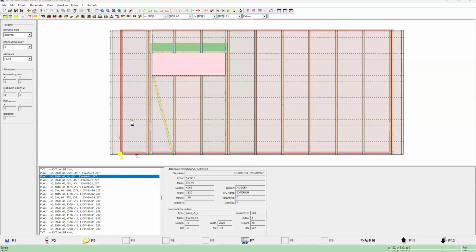ArchiFrame has added markings for every fourth or third cladding piece, because the operator places these manually on the table, and then the machine shoots the nails, and it has to match what is modeled in ArchiFrame. Otherwise, the nails will be in an incorrect place.